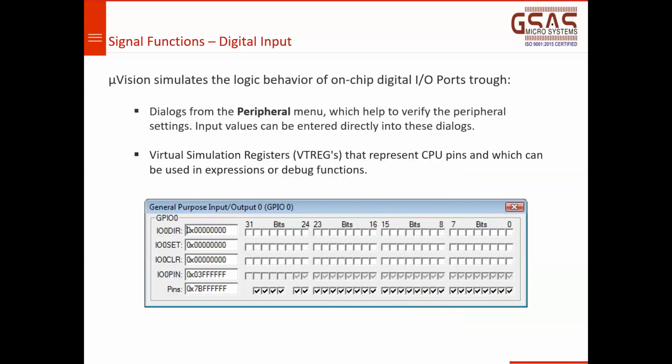Now coming to digital input. In microcontrollers, we have GPIO pins. If a particular processor has many functionalities and many peripherals, but the vendors want to keep the pin count low, then the silicon vendors, meaning semiconductor vendors, multiplex the functionality of the GPIO pin with various other features.